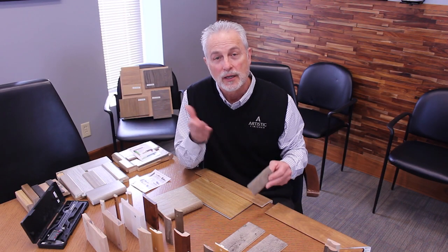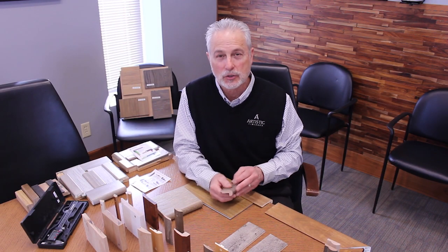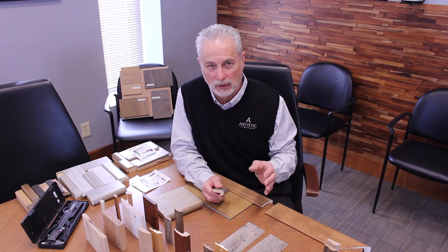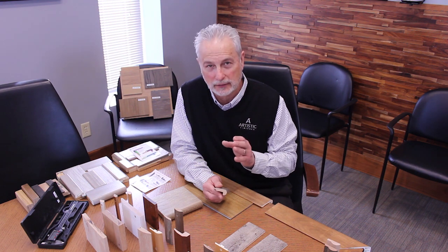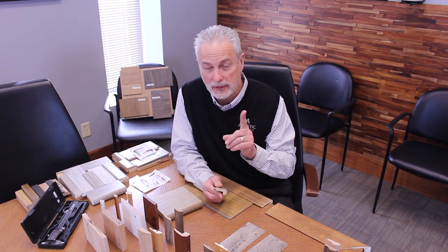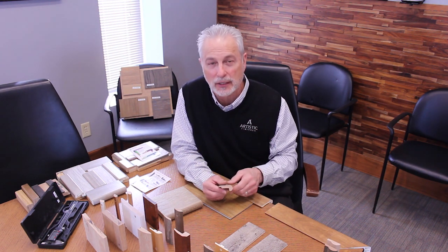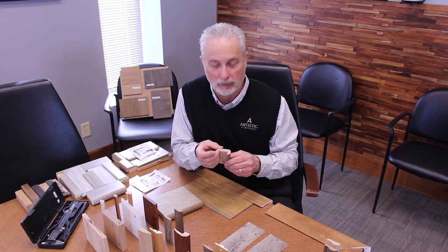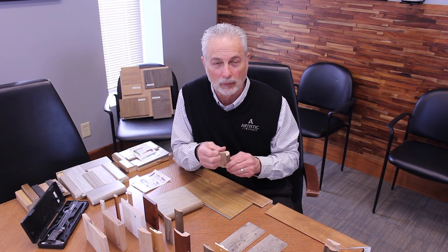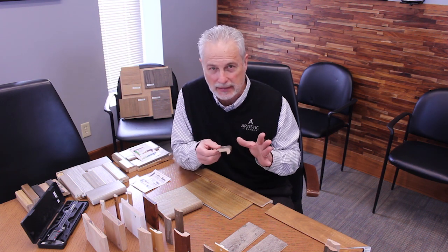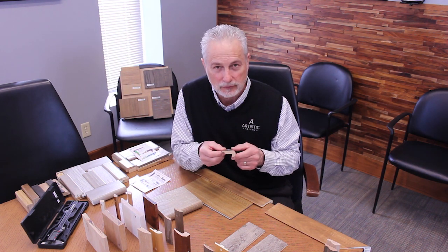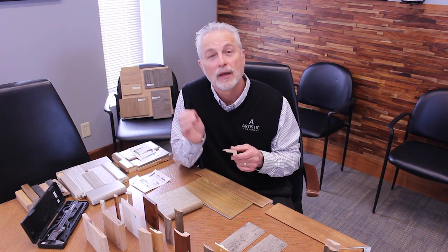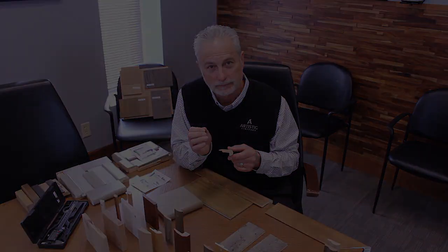Overlapping stair nosing. When would that be used? The key term here is floating. If the floor is going to be floated, you're going to most likely be using, not always, but most likely, overlapping profiles. And of course, stair nosing is one of those that does have the lip available in our profiles in many different sizes for a stair nose to be installed with a floating floor.